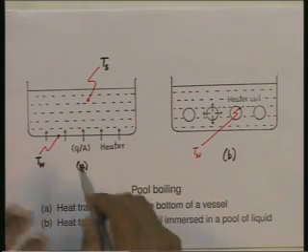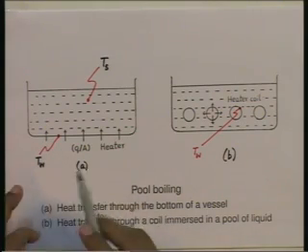So, boiling is going to take place and we are going to conduct the experiment as follows. We are going to systematically raise the value of T W. T S is fixed, it depends on the particular liquid and the condition of pressure that it is in. So, we are going to systematically raise the value of T W. We will first work with say T W minus T S equal to 1 degree, then T W minus T S equal to say 2 degrees, then 5 degrees, then 10 degrees, then 20 degrees, then 100 degrees, as much as we can go.